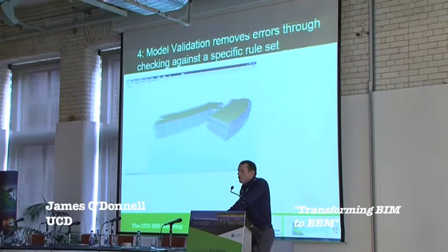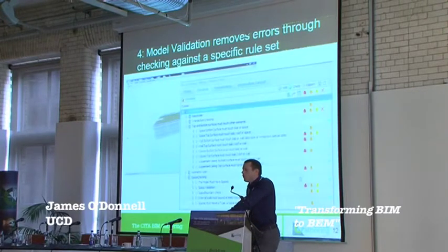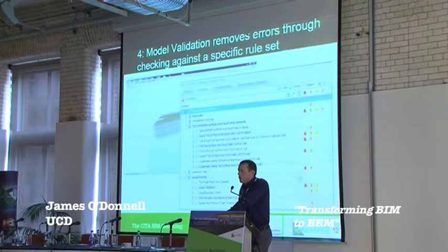Okay, so we export then to Solibri Model Checker, which I think most of the audience here are familiar with, the model checking environment, but we developed a customized rule set for this approach. So this is based on, again, those tolerances that I talked about earlier. We also ensure that, for example, walls must touch ceilings, walls must connect with the slabs, and that the zone boundary is flush with the wall, etc.